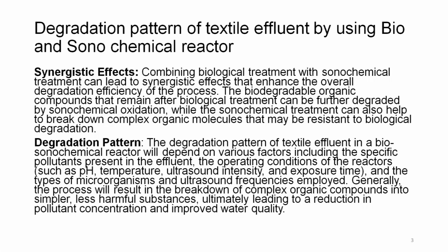bio-hyphenated sonochemical reactor will depend on various factors, including the specific pollutants present in the effluent, the operating conditions of the reactors such as pH, temperature, ultrasound intensity and exposure time, and the type of microorganisms and ultrasound frequencies employed. Generally, the process will result in the breakdown of complex organic compounds into simpler, less harmful substances, ultimately leading to a reduction in pollutant concentration and improved water quality.